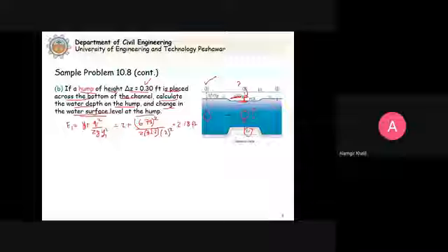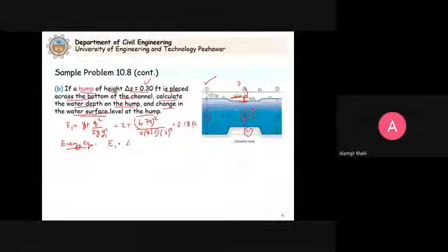Now if we have critical flow, we can write down the energy equation. We will ignore the losses; this is given in the problem. So we write down E1 equal to delta Z critical plus... Actually we want to check whether this point 3 is less than the critical hump height or greater than the critical hump height, so accordingly we can solve the problem.